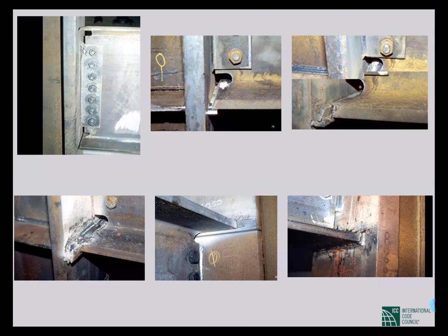You can see, in the second picture at the top, at the bottom, for bottom flange welding, some backing has been provided. Some metal steel is placed under the bottom flange, and tack weld has been done so that it is attached to the bottom flange. So that is the backing material. Now some weld tabs have been placed.